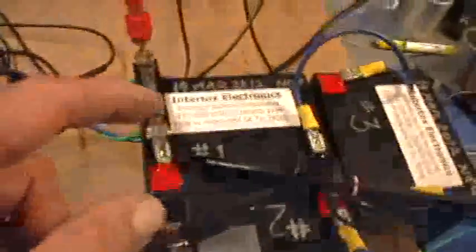Where is it? Oh, sorry. This is the purple trace. This is the trace across the battery, not the common drains. There's the purple probe, and there's across the battery right there. And then this trace is the green trace. And the green trace, as we know, is the MOSFET common drain on the load side of the transistor.